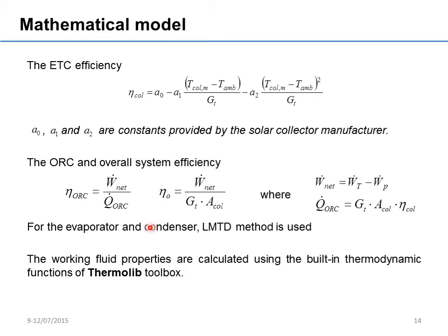To evaluate and determine the heat exchanger area for the evaporator and the condenser, the log mean temperature difference method is used. The working fluid properties are calculated using the built-in thermodynamic functions in the Thermolib toolbox.